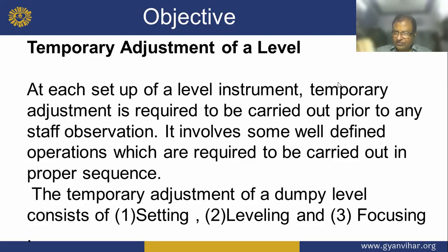It involves some well-defined operations which are required to be carried out in proper sequence. The temporary adjustment of a dumpy level consists of setting, leveling, and focusing.